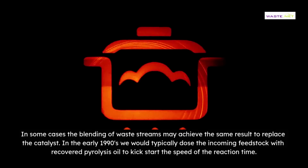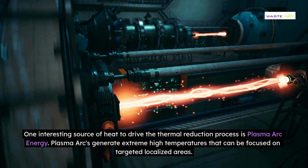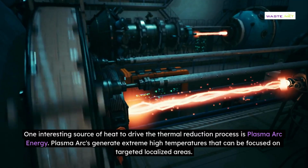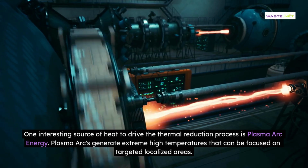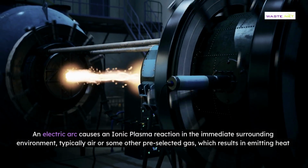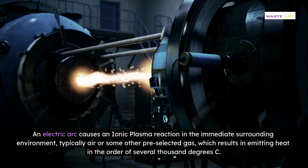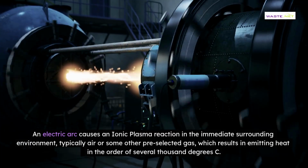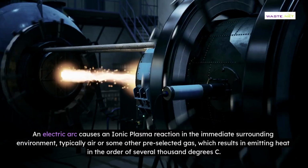One interesting source of heat to drive the thermal reduction process is plasma arc energy. Plasma arcs generate extreme high temperatures that can be focused on targeted localized areas. An electric arc causes an ionic plasma reaction in the immediate surrounding environment, typically air or some other pre-selected gas, which results in emitting heat in the order of several thousand degrees Celsius.